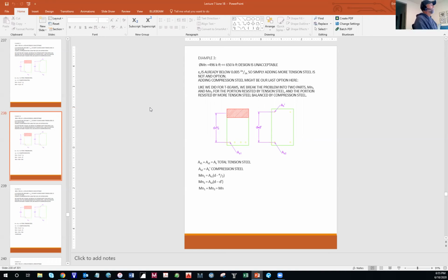But I'll give you this. On homework 3, question 2, you do not need to evaluate the 3 different loading conditions with the 1.4 dead load case. You can look at them with just 1.2 dead, 1.6 live, because that clearly is going to be the one that controls.